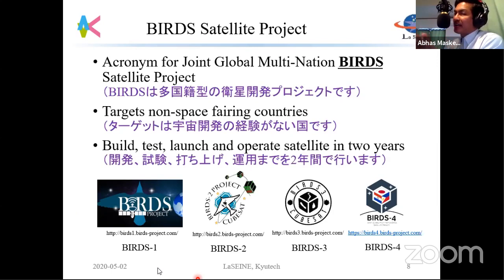So let's say we are downloading an image. We see that a certain part of the image is missing, so we have to download it again, right? We see that 5 to 10% or 15% of the time. The reason that happens is probably because the antenna is not calibrated properly, or there is some kind of interference, like some weather condition. Initially we could have 0 packet loss, then it goes to 5%, then 10%. Then we calibrate the antenna to azimuth again, and once we calibrate that, we reduce the packet loss.